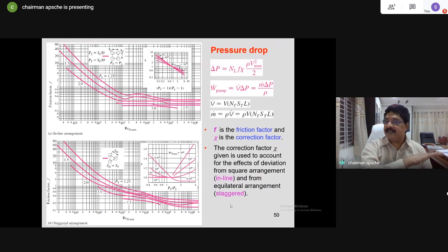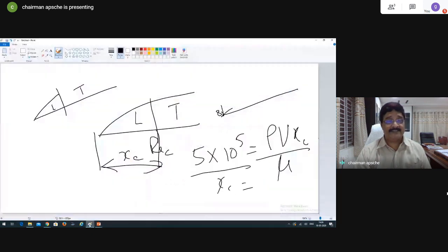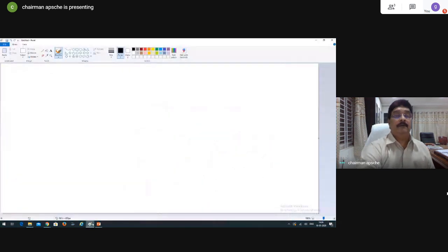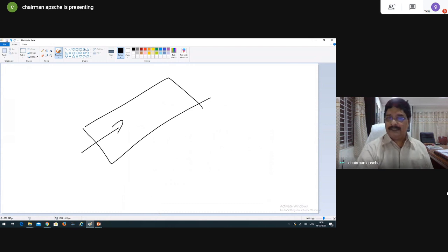For flat plates, it is the length of the plate along the fluid flow direction. And again, let me clarify. Having said that, this just struck my mind now. If a plate like this, fluid flow is happening in this direction. Say I said in the earlier example, it is 3 meters, and therefore LC will be 3 meters for you.